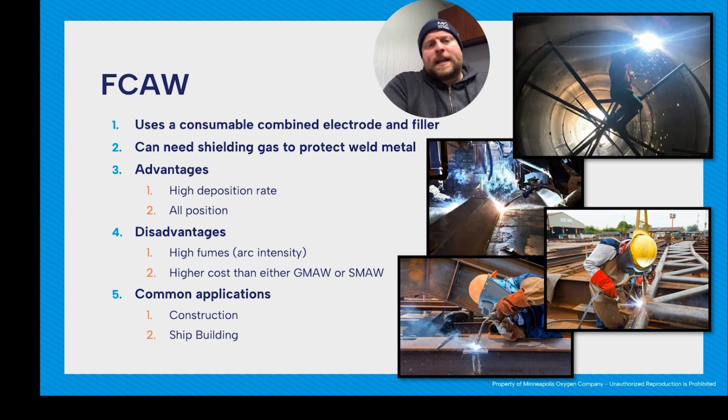All right, FCAW, so that's flux cored arc welding. This uses a consumable combined electrode and filler. It's kind of like a mix of your MIG and stick. So the actual filler is a hollow wire that has flux inside. So it's kind of like an inside out stick electrode. And then it's run on a MIG machine. So it's on a spool, dispensed the same way with a gun. Squeeze the trigger, out comes your wire, your electricity, and your gas.